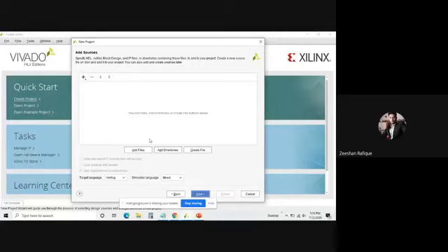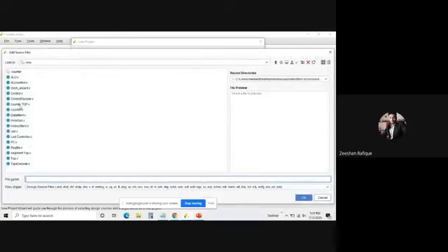Here you have to add the source files which you got from the Chisel generated code. So just click on add files. These are all the files which were created by the Chisel code, as shown before. Many of the files are generated by the Chisel code. A few of the files I have added myself, because when you are turning on the LEDs on the FPGA, you need some extra code to drive those LEDs. So let me show you that.